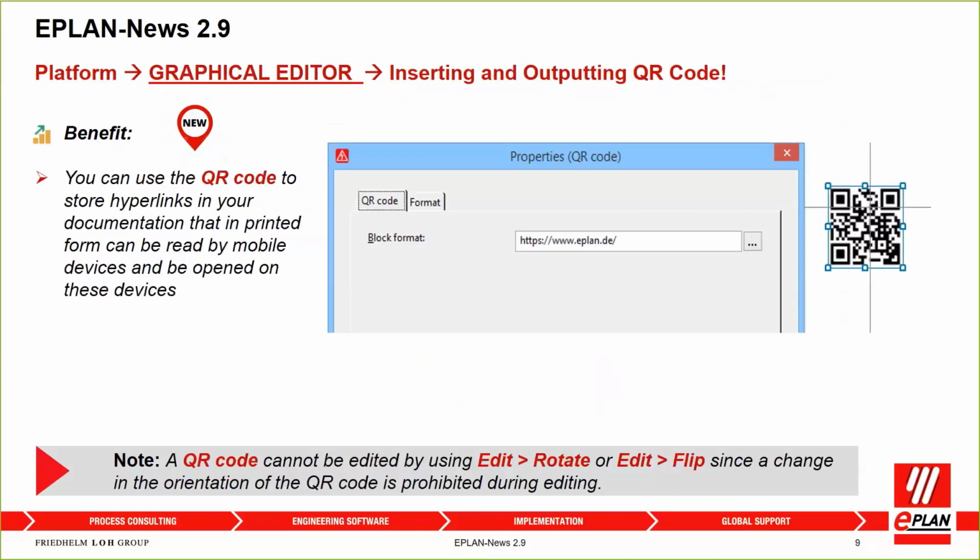Okay, we can now insert and output QR codes. QR codes are pretty useful for bringing up data sheets, websites, manuals, anything that you can bring up via a URL. You can use the QR code, scan it via an iPhone app or a QR reader. You can insert them similar to images by using Insert QR Code. Type an address and it'll convert that address into the QR code.